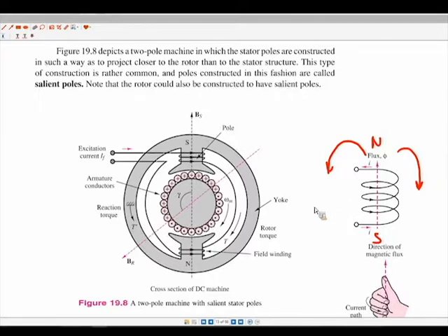And so that gets confusing when you start to talk about, say, the stator location, which is this big box on the outside here. In the book and other books, it denotes this side as north and this side as south. So if we were to map this electromagnet to this, we would say each of these stator elements has a north and a south associated with it, just like this one has current running exactly the same way. Okay, so you can see how it's starting to get a little bit more complicated here.